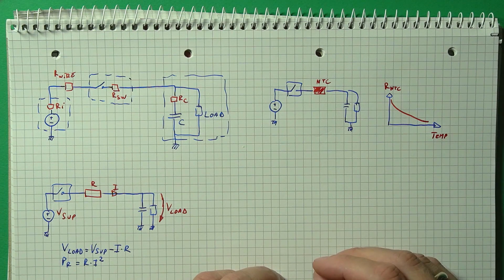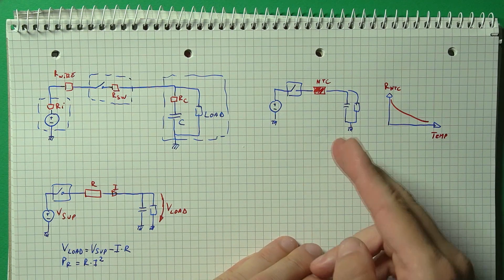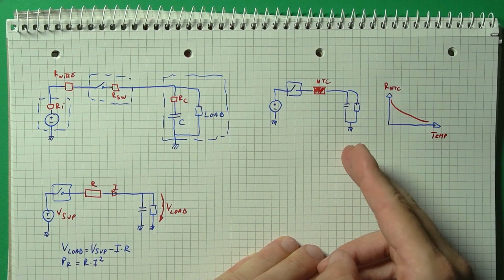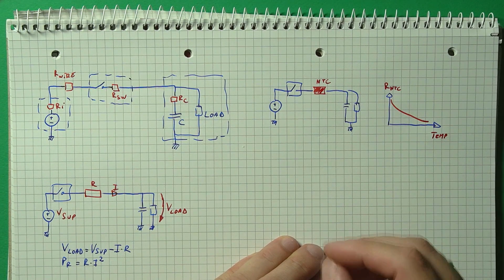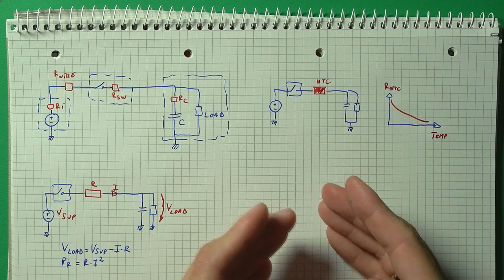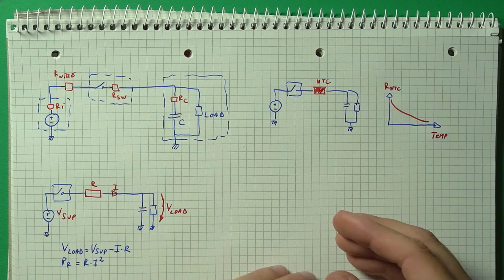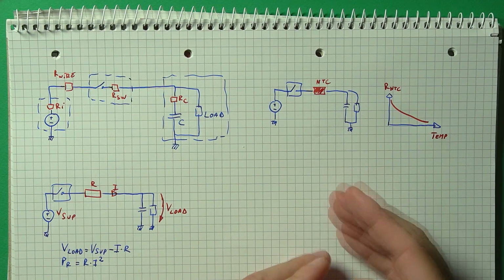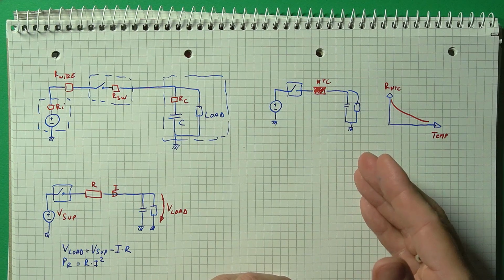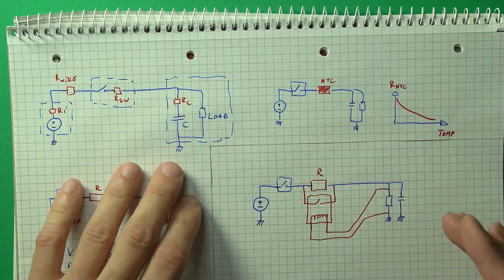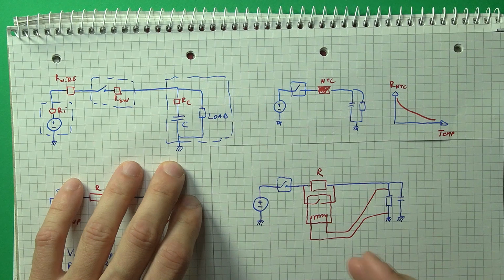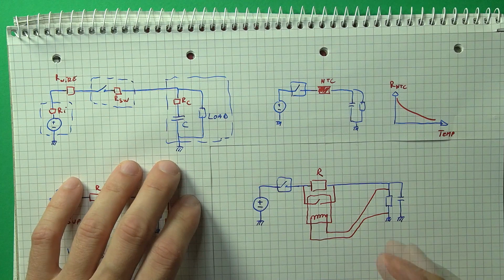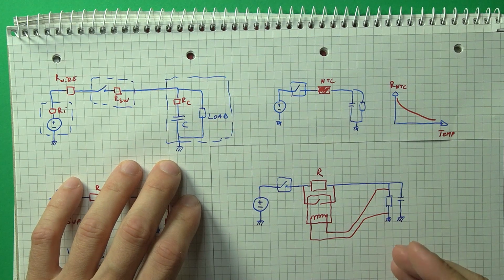This is a good solution as long as the time it takes for the capacitor to discharge during turn-off is similar to the cooling period of the NTC thermistor. Otherwise, a set of fast turn-on, turn-off cycles could get you to have a hot thermistor and a discharged capacitor, which is not good since you would be losing the current limiting benefits. The other, more complex way involves using a relay to shunt the resistor after the output voltage reached a certain value. This way you remove the permanent resistive loss, but you need to keep the relay active.